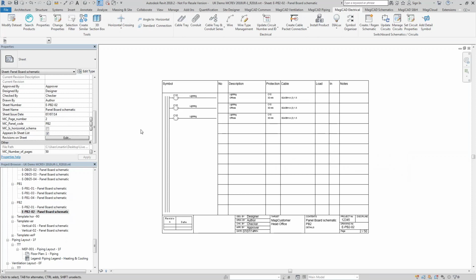And then if you're using an external calculation software, then you can also use these to plan out your circuits in your calculation software, run your calculations, maybe change some information as required as a result of the calculations, populate that information back into these schematics, and then again you can push that information then into your Revit model based on whatever process you've done with your external calculation software.